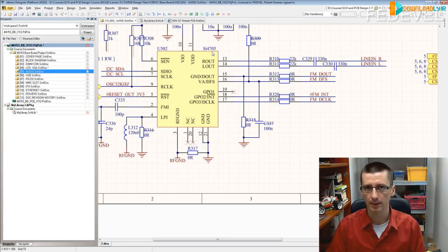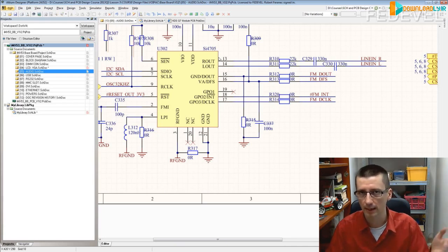What may very easily happen is the SI4705 which you found on the internet may be actually a little bit different than this one which you need to replace in your reference schematic, because these pins can be placed in any order or somewhere else. So there is no one-to-one replacement. And you may end up editing the downloaded schematic symbol, which takes some time again.